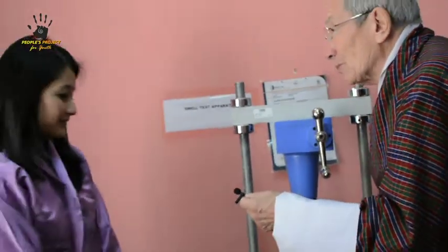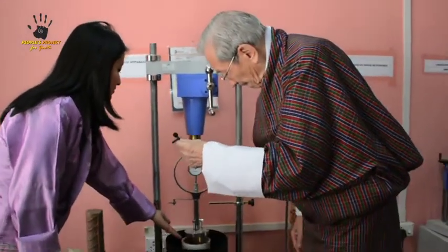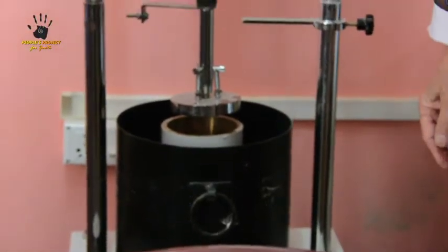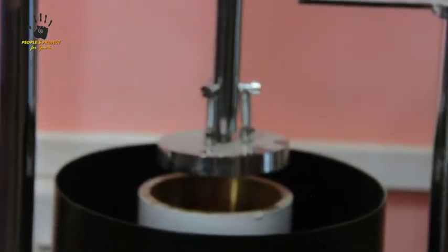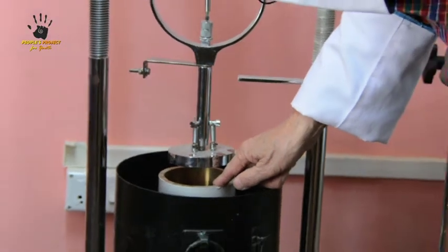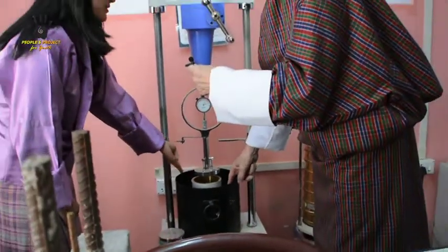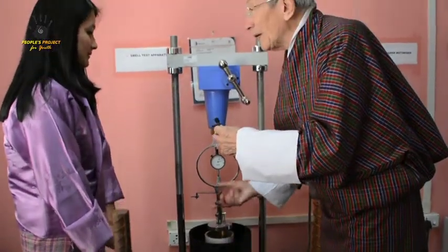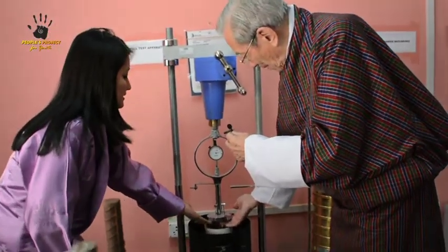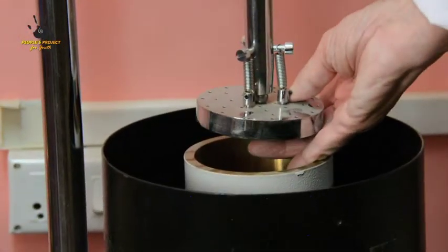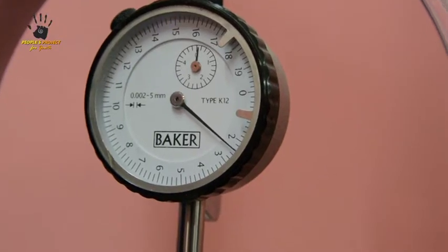Where do we put the soil sample? We insert these samples in this place. In there, in this cylinder, cabinet, yes, sir. And then we apply pressure. By turning that. Yes, sir. And it squeezes the soil in this cylinder. Yes, sir. And then we pour water. So you pour water inside the outer cylinder. Yes, which makes the soil wet. The soil swells, pushes up there, and I don't know whether the camera can see, as we push up, the little needle there changes, so we can measure how much the soil swells.